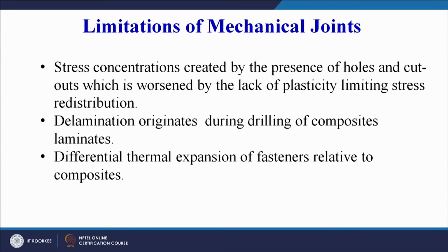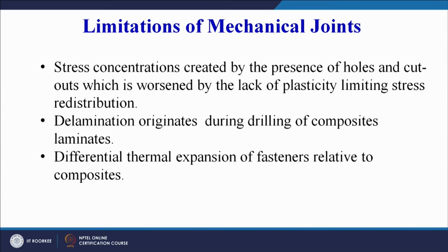So, stress concentration, as I have already explained, is created by the presence of holes and cutouts, which is worsened by the lack of plasticity, limiting stress redistribution. Usually, stress redistribution does not happen that easily in the case of holes and cutouts in composite parts or plastic parts or polymer based components. So, the stress redistribution is relatively difficult, and therefore, there is an issue in the context of the stress concentration. Delamination originates during drilling of composites.